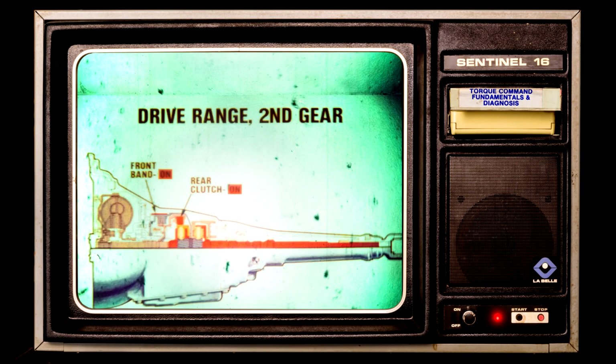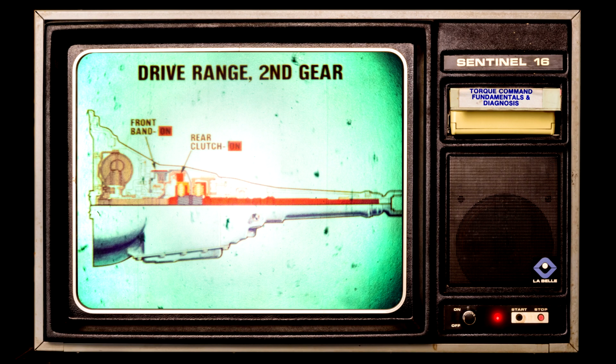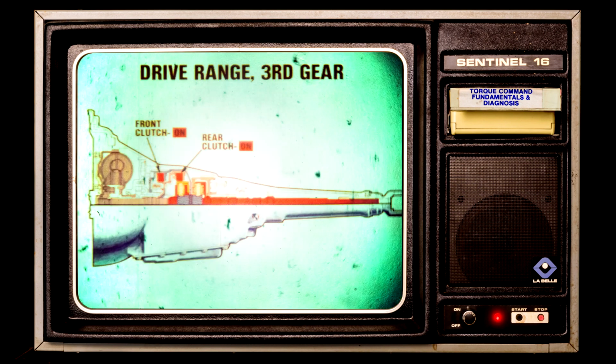In drive range second gear and in manual second, the front band is applied and the rear clutch remains on from first gear. Torque is now transmitted through the planetary gears in reduction of 1.45 to 1. In third gear, both front and rear clutches are applied. This locks both members of the planetary gear set together, connecting all transmission parts into one common unit from the engine to the output shaft, a 1-to-1 ratio.